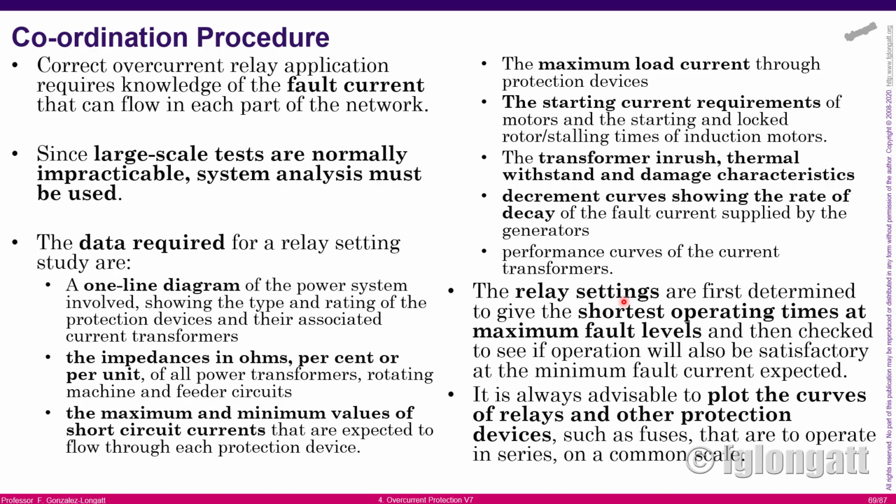But the first thing you need to do is understand and have a full picture of the fault short circuit currents in your system. You must know the current that is flowing in any part of your system.